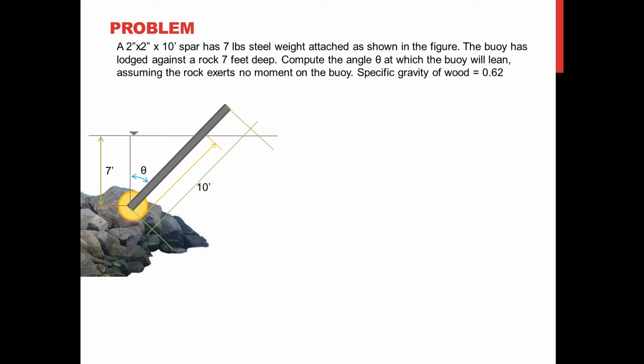So notice here that our total length of the spar is 10 feet. So that is actually parallel dimension to your spar. If we could only determine this length, then we can just simply determine our theta by using cosine function.